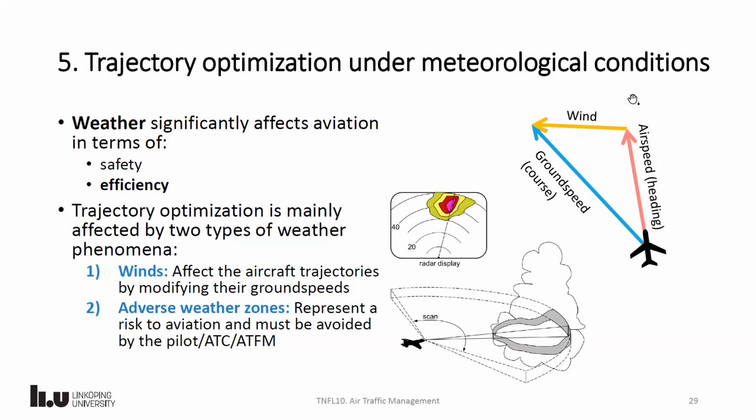On the other hand, if we have a wind that is coming towards the aircraft, we call that a headwind. The aircraft will feel like it is slowing down. The airspeed is the same in both cases, but the ground speeds are not. And this is very important because we want to fly from place A to place B, but those A and B points are on the ground. So we want to look at our direction above the ground, because finally we want to get from one point to another and not just drift in the air.